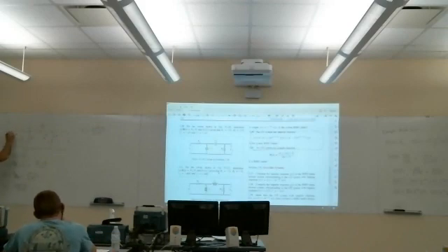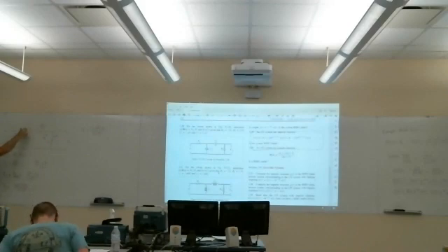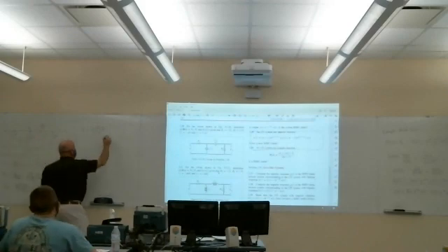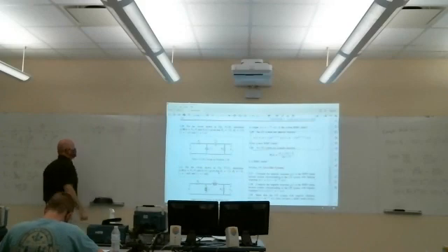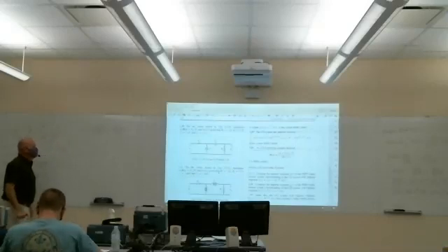With the current direction, this is the polarity of that voltage, so that's plus minus. Again, the same here. Well, actually, I don't need to take Ix times that impedance because that voltage is Vx. So plus 10 to the 6 plus 4s over 2s.